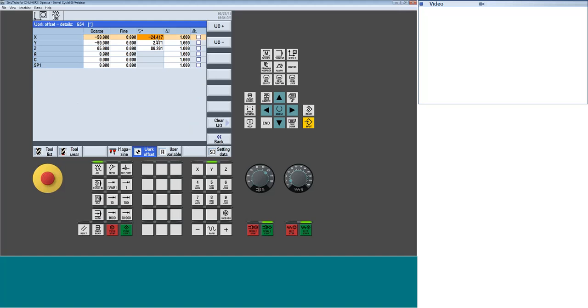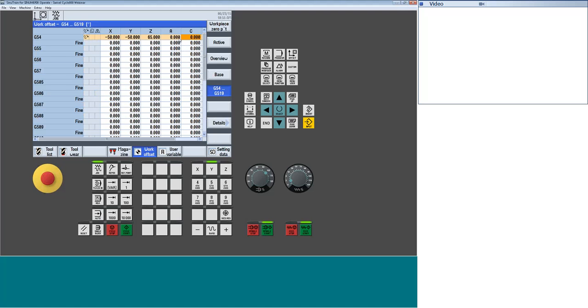When I position based on my coordinate system, but I set it up based on these rotations, these will start to come into play with the tool carrier when I'm using swivel cycle, but not necessarily when I'm just positioning axes. That's why I was saying earlier, depending on how you program it, it's important to know that when I'm going to set it up. So if I was just strictly positioning the zeros and not using the swivel cycle, then I'm not going to get those offsets into play. It's not going to compensate properly.